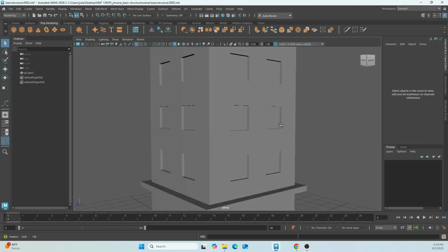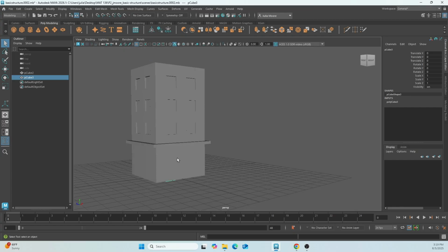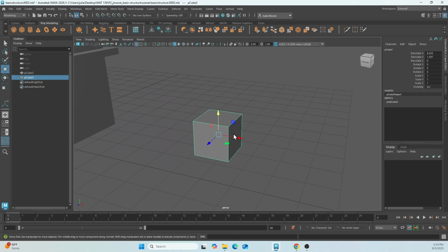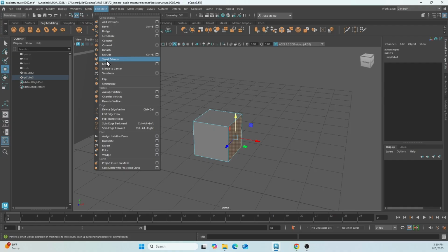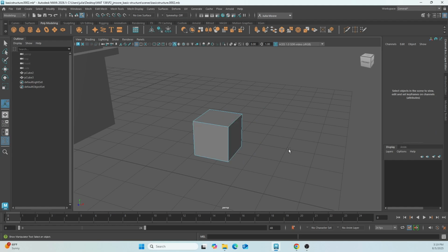All right, we got some windows. Now, it is important to know when you're making an extrusion, and I'm going to illustrate with a cube again. Go to Face Mode. I'm going to go right here. When I go up to Edit Mesh, Extrude, and I haven't done anything yet, and I click away, so I deselect that extrusion, you can't tell, but that is actually just still sitting there. I've still extruded a face, and it's sitting on the face, the original face beneath it.